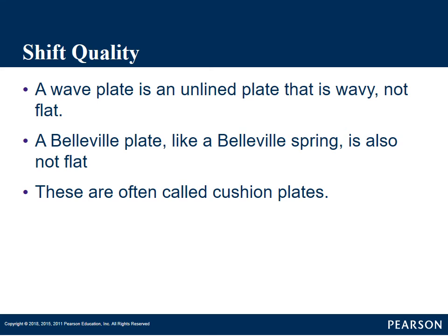And that's almost always the one connected to the input shaft of the transmission. So we're always getting power from the impeller and the turbine of the torque converter through the input shaft. So the clutch pack hooked to that input shaft is always engaged, especially in forward gear.